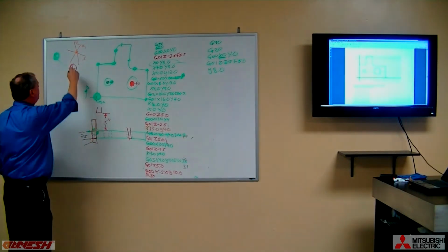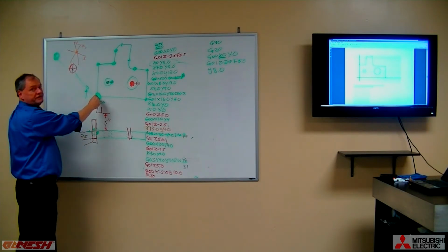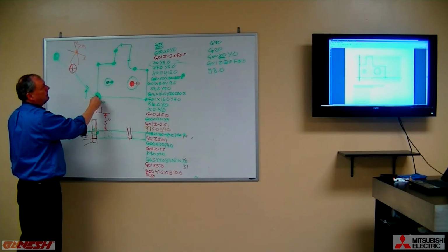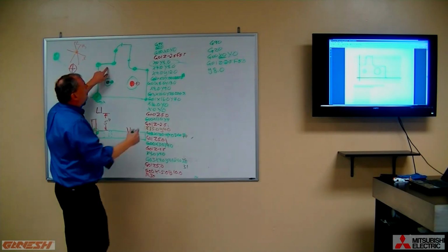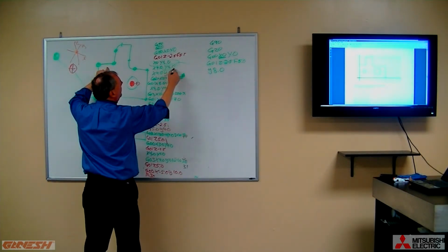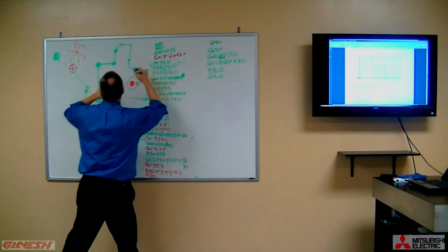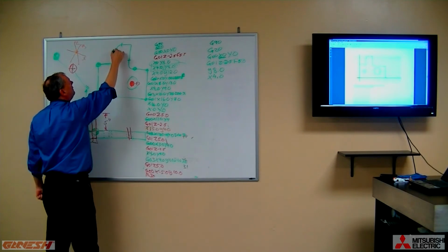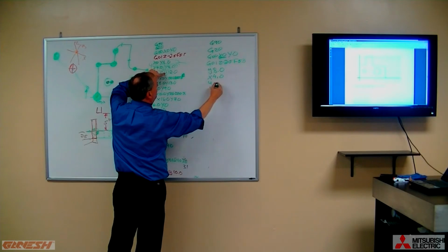What that does is it'll make a rapid position, get us over the part. It will bring Z down. It knows it's sitting at X0 right now. So therefore, I don't need to repeat the word X0. I can just say Y8.0. And now look, this next block, we're already at Y8.0, so I don't need to repeat that. I just will now say X4.0. And now it's going to make just an x-axis move to there. And now we're going to go up to this point, which is simply a y-axis move, Y12.0.